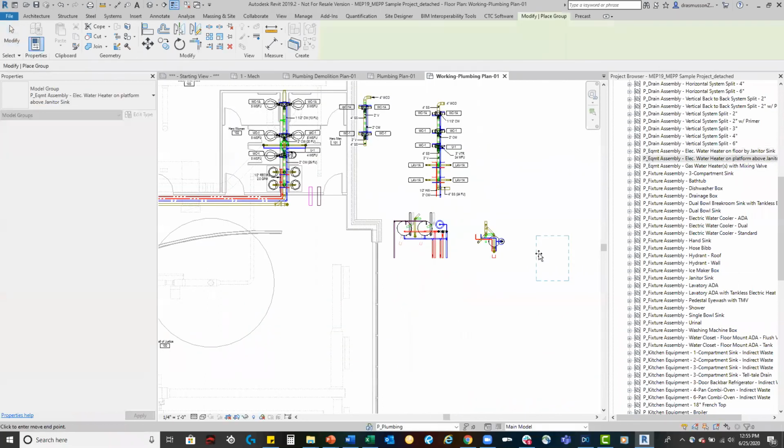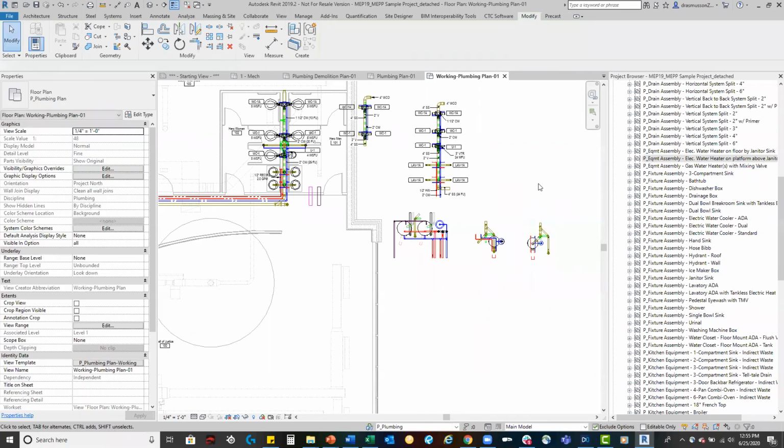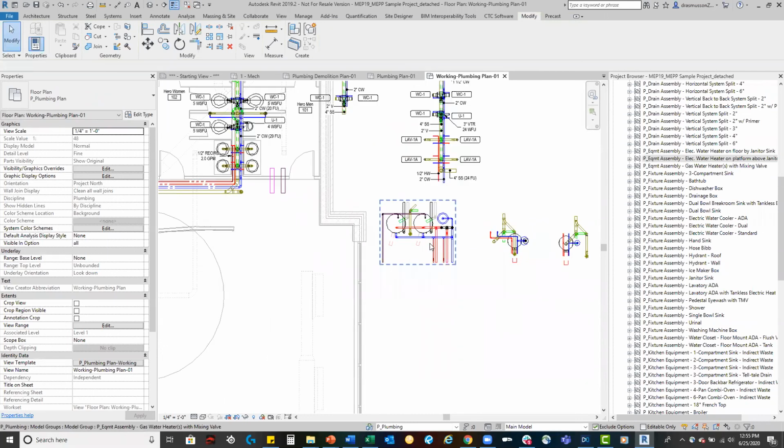And then on platform. Now it's important to keep in mind, guys, that as I'm showing you this, this may not be what you would designate. You can edit these groups at any time. You can change out the system types, you can change out the pipe types, you can change out the pieces of equipment, you can really use these to drive your standard. And the whole idea behind this is not to necessarily do all the work, but to get you way farther faster than you typically would if you had to be doing this by individual part and piece.